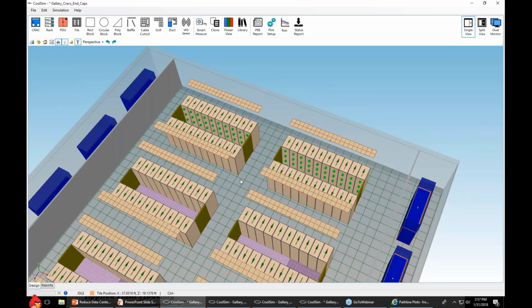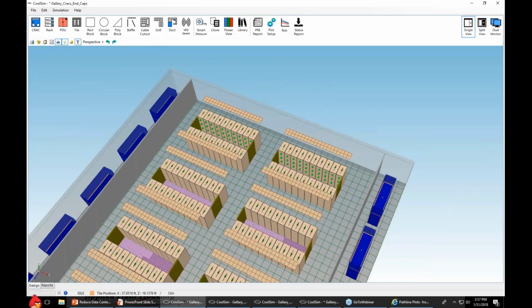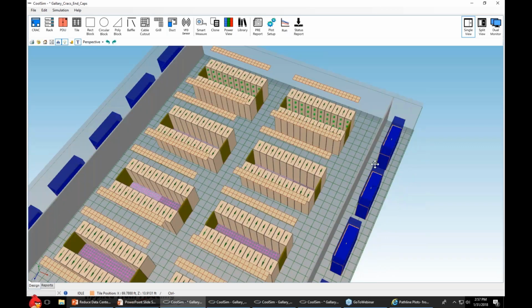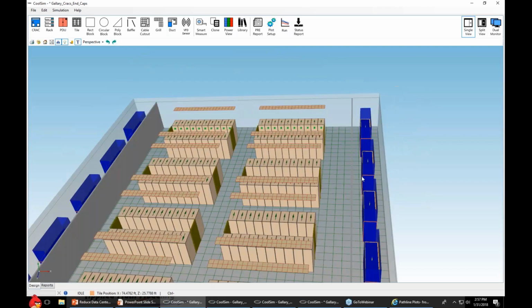And that's for the VFD. Now, the other thermostat they often put in place is the one for chilled water. It modulates the chilled water valve. It is the supply air temp thermostat. Those by default come in the return. Believe it or not, they're stuck in the return of the cooling unit itself, and you've got to move them. Now in CoolSim, we have an option where you can move them to the supply. That's generally what people do, is move them to the supply, so that the thermostat that controls the cold air is actually on the supply.